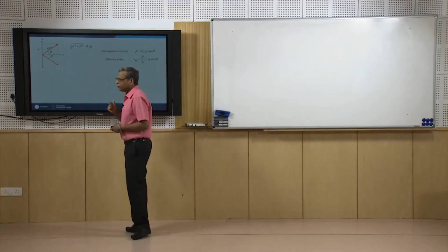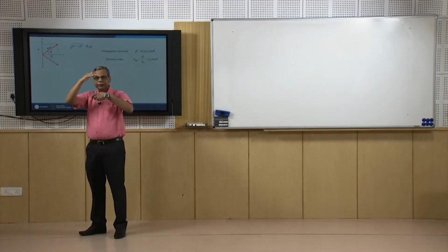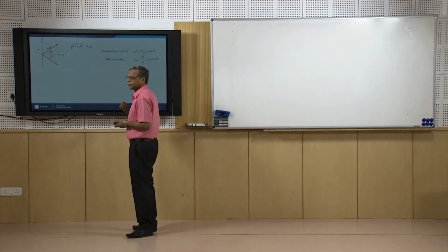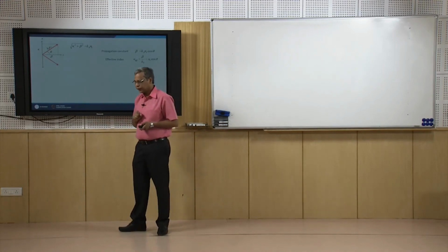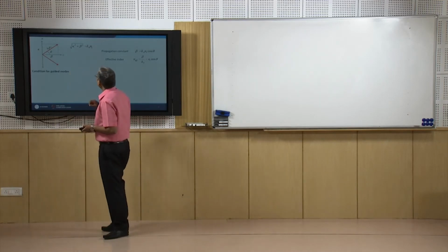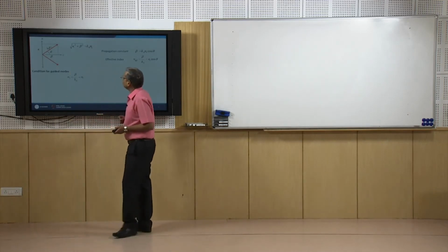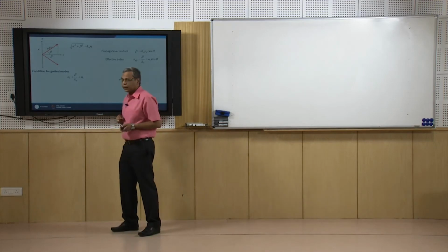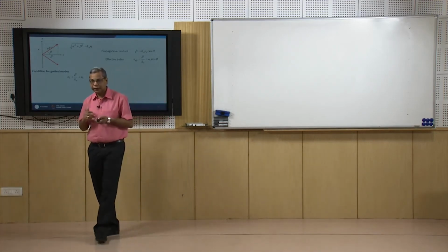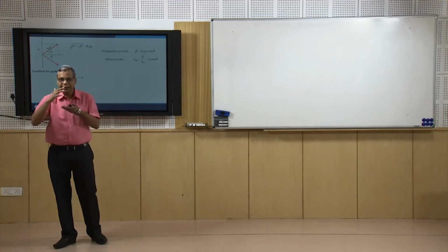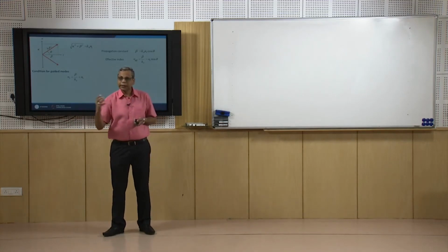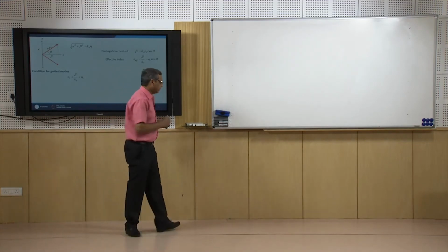However, this standing wave pattern flows in the z direction with propagation constant beta, exactly in the same way as the planar mirror waveguide. So, these modal fields are the standing wave patterns in the x direction, because I have E y of x, and this E y of x is propagating with propagation constant beta.